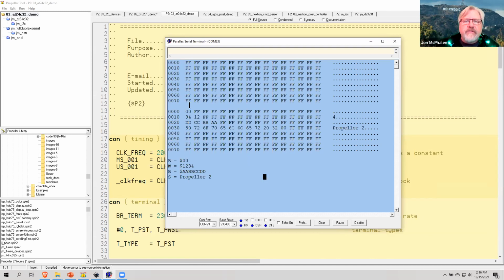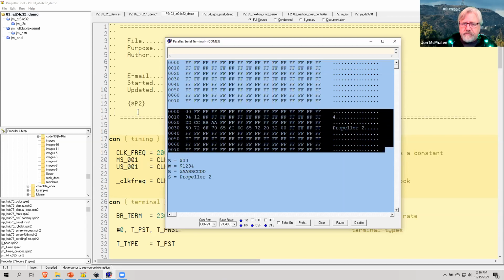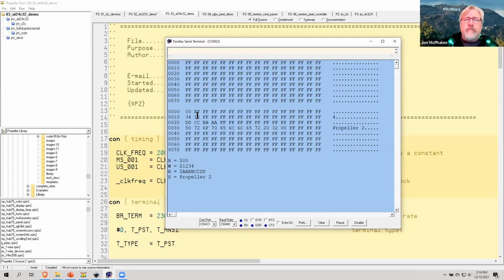So here I've written a byte, a word, a long, and a string into this EEPROM, and then spit that range of values back out. I want to show you, this is pretty easy. 0 is 0. We throw around terms like little endian and big endian all the time, but this lets you see it because these addresses are ascending, going that direction.